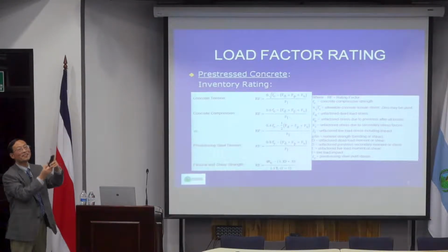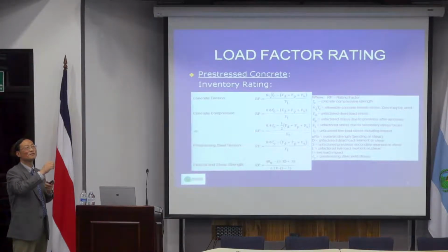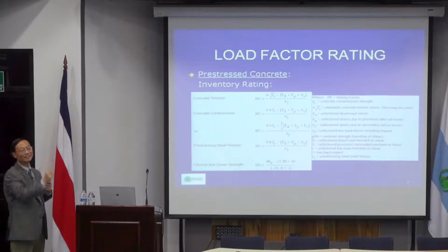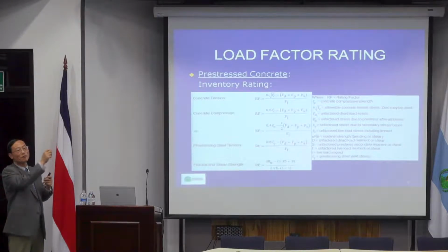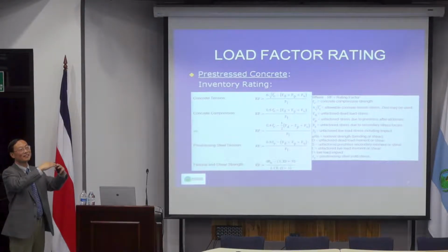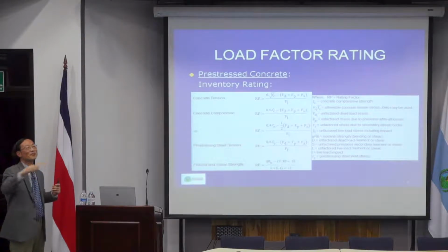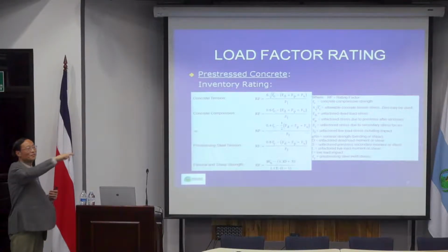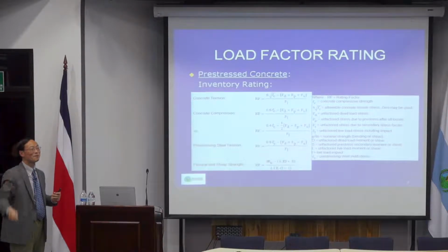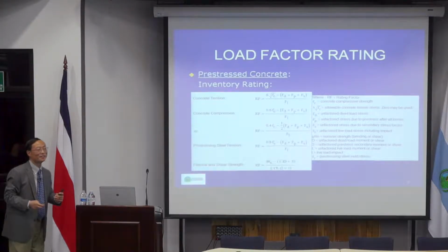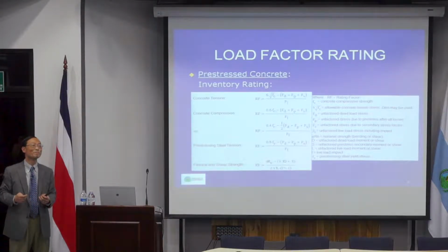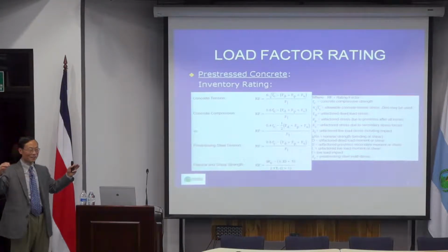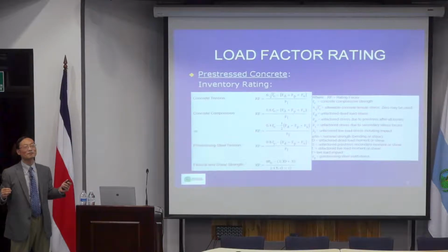So now we have 10 tons, which is almost an equivalent force pulling it down to make it support. In other words, you produce an additional bending moment. A lot of people may think it's an imaginary bending force, but actually it's a real bending stress, a real bending moment. That's why in the design, the secondary bending forces should be calculated and should be part of the design.